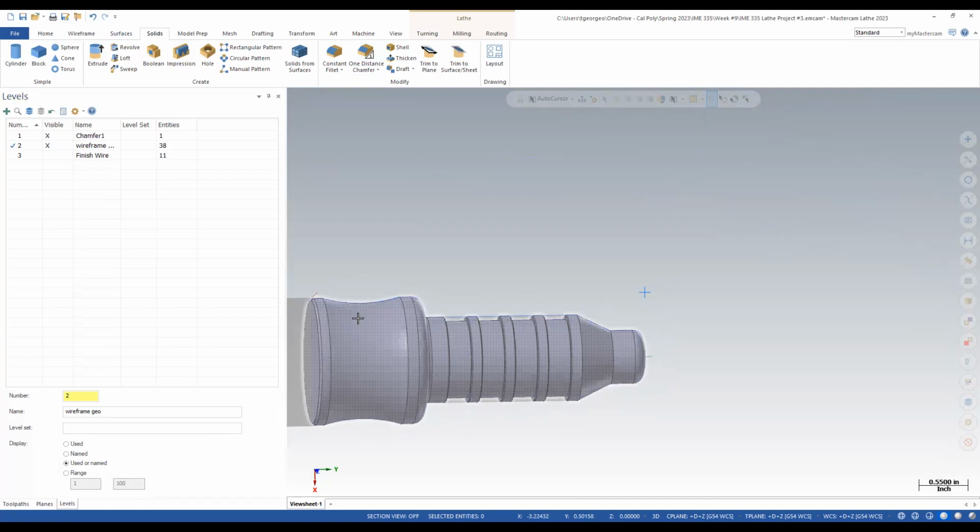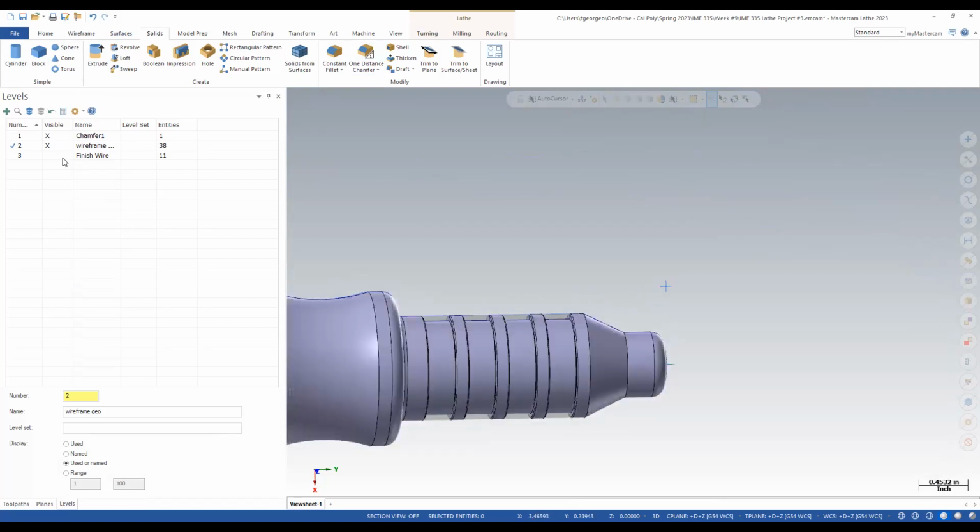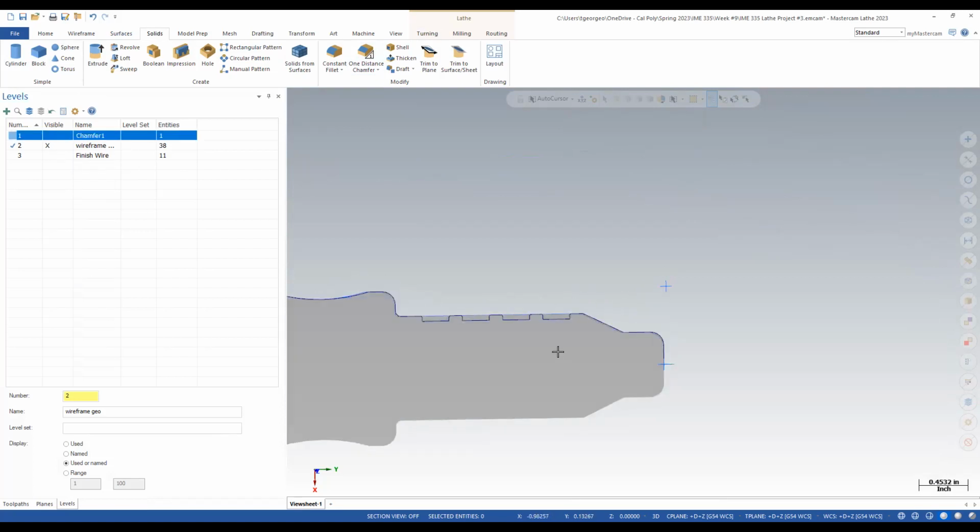If not, what could you do? Go to your SolidWorks, chamfer it, merge it back in, and then just do another turn profile real quick to show that for the grooves only, and just have one for the grooves. Does that make sense? Oh, your wireframe chamfers. If you could just throw some chamfers on your wireframe, guaranteed. I could show you that right now. Hold on. There's more than one way to do everything, right?